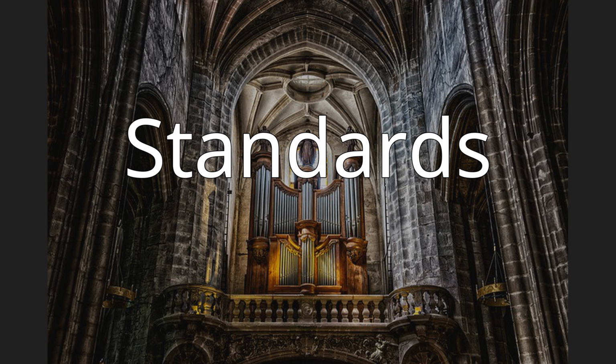Organizations that promulgate piping standards include ASME, the American Society of Mechanical Engineers, B31 series, ASME B31.1 power piping, steam piping, etc. ASME B31.3 process piping, ASME B31.4 pipeline transportation systems for liquid hydrocarbons and other liquids and oil and gas, ASME B31.5 refrigeration piping and heat transfer components, ASME B31.8 gas transmission and distribution piping systems, ASME B31.9 building